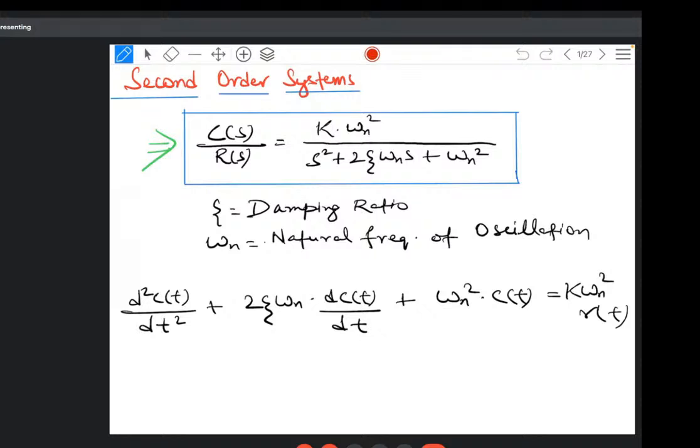If you remember, yesterday we completed the steady state response part. We calculated the steady state error due to any random input, due to disturbance, and due to different standard time domain test signals. We calculated it for different types of the system, that is type 0, type 1 and type 2. Then we generalized the error coefficients with the type of the system. Then we solved several numericals on that.